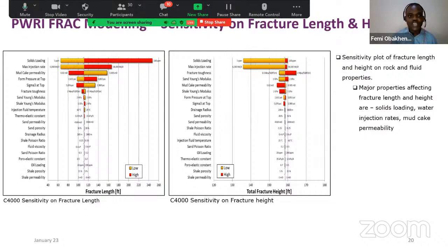And then your injection rate, how much do you want to inject? Can you do with more wells and inject at a lower rate, or fewer wells and inject at a higher rate? This is the information this fracture modeling can tell you, so that you can build a robust produced water injection system.